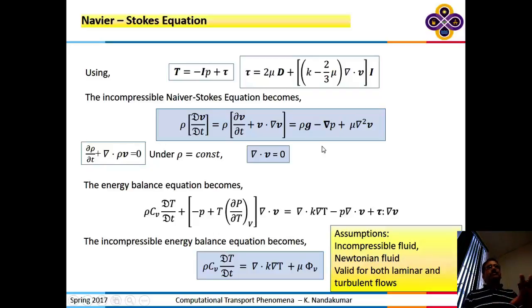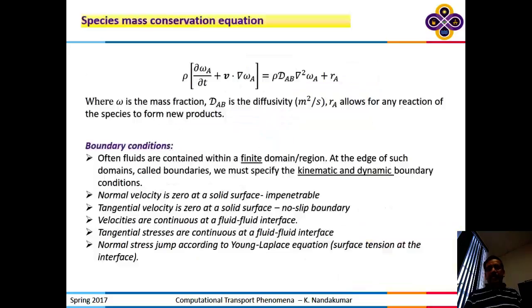And once we open up COMSOL, we will see the same equations, okay? And we will see how easy it is to set up. The problem is decoupled into one of specifying geometries, boundary conditions, picking the physics from this, and coupling them to study various types of problems. And that's the place where you will learn how to present your own project using these tools. Now, those are the governing equations that allow us to track momentum transfer, heat transfer, and mass transfer of a species in a flow environment with chemical reaction, with thermodynamic equilibrium, etc. They're all kind of superimposed onto these fields.